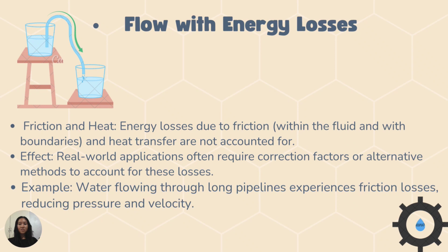These losses are typically attributed to the conversion of mechanical energy into thermal energy. The presence of energy losses complicates the analysis of fluid flow systems, particularly when using simplified models or equations such as the Bernoulli equation. While Bernoulli's equation assumes idealized conditions with no energy losses, real-world applications often involve energy dissipation mechanisms that cannot be ignored. Consequently, relying solely on Bernoulli's equation will lead to inaccurate predictions of pressure, velocity, and other flow parameters.